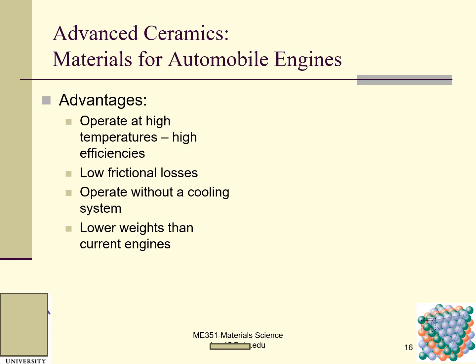So advanced ceramic materials are another category. Materials for automobile engines. Advantages: operate at high temperatures and high efficiency, and low frictional losses. Why? Because it has very, very high hardness, so frictional losses will be very, very low. And they operate without a cooling system. You do not need a cooling system because this material has a very, very high melting temperature. No worry about the cooling, the overheating,